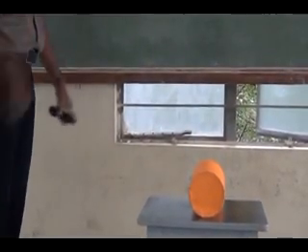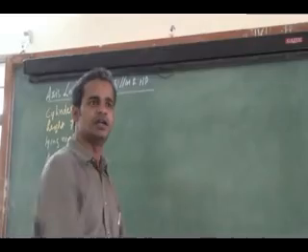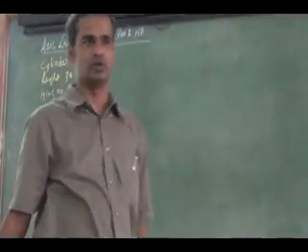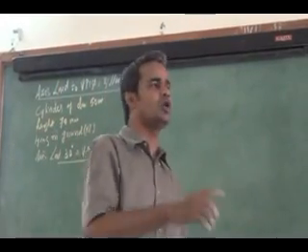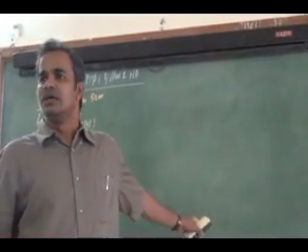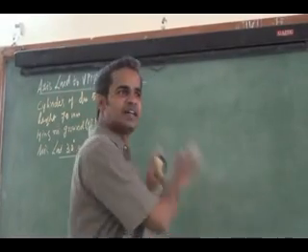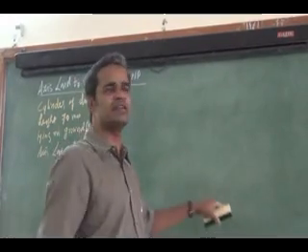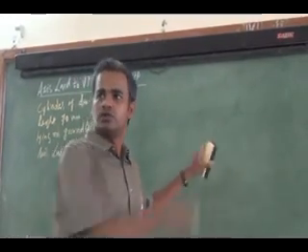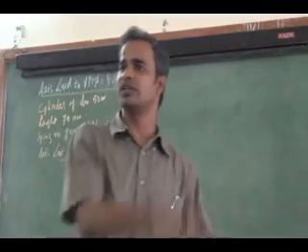Draw the circle and divide it into 12 divisions. You get the top view. Then tilt the top view to 30 degrees, redraw it, and get the final front view. You don't need to show all the generators. Just divide the base circle alone into 12 circumference points. Is the problem clear? Draw the circle touching the reference line, above the reference line, that is on VP, since the axis is inclined to VP. Then proceed to the top view, tilt it to 30 degrees, and get the front view.